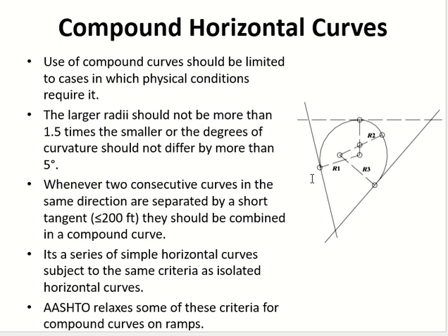And why do we provide compound curves? To save space. Whenever we design highway ramps, ramps take a lot of space and they have a lot of cost as well because you have to make them elevated. So to save the space and the material, we make compound curves for the ramps. Even in parking spaces which go from one floor to the other, we have to make ramps. Those ramps are also compound curves because they save space.